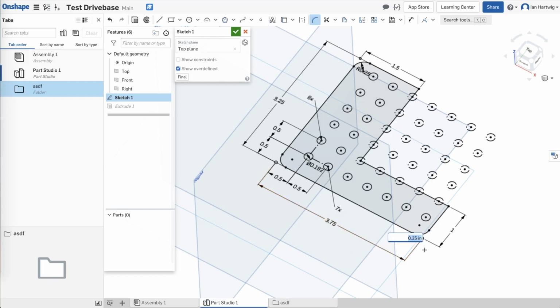And because this is an extra feature of Onshape, because I selected the same radius for all of them, it actually made them all equal radius, and it only drew the dimension once. You can see it up here. What that means is that if I want to change this, let's say I think that a 1/4 inch, 0.25 inches is too much curvature, I could change this to an 1/8 inch. And now you can see that they all change together.